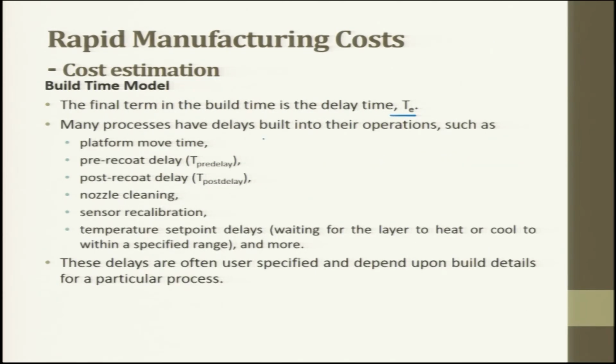Many processes have delays built into their operations, such as platform move time, pre-recoat delay, post-recoat delay, nozzle cleaning, sensor calibration, temperature set point delays, that is waiting for the layer to heat or cool within a specific range, and so on. So, this is actually setup time.